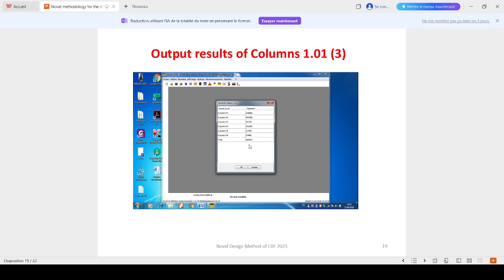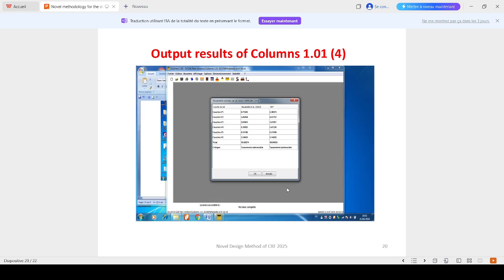In this case it is about 40 something centimeters, which is inadmissible, and the settlement of reinforced soil is about 80 centimeters, because it is a very big tank with several compressible layers. So the admissible settlement was considered to be about 80 centimeters.